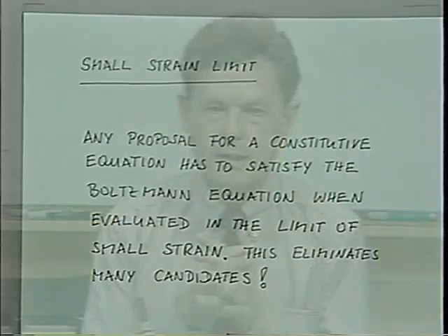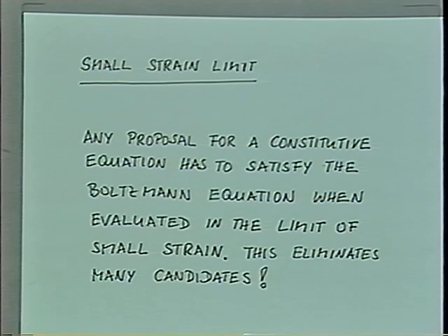Let me stress this small strain limit a little further. Many constitutive equations have been proposed which don't reduce to the linear viscoelastic model at small strains. And we don't want to lose all the information which we already have about linear viscoelasticity.